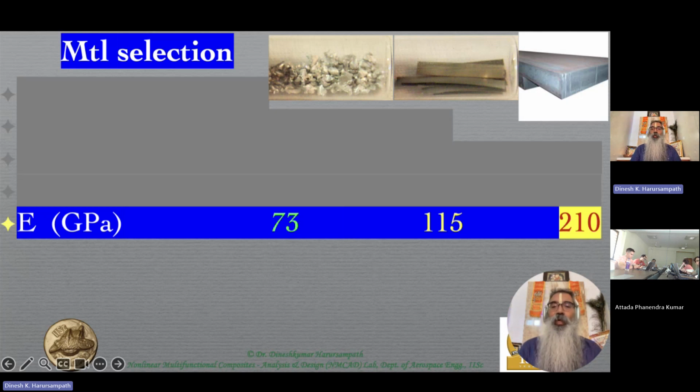So here, as I said, there's not much of a range across the aluminum alloys, but you see about 1.5 times that is what titanium alloys are. So the relative change is not as much, and steel is about double of that of titanium, which means about 3 times that of the aluminum alloys. And so once again, you see a similar trend that we see that titanium is better than aluminum and steel is better than titanium, and therefore I'm highlighting the last column here, both in the case of the sigma U as well as the E, that is the Young's modulus, right?